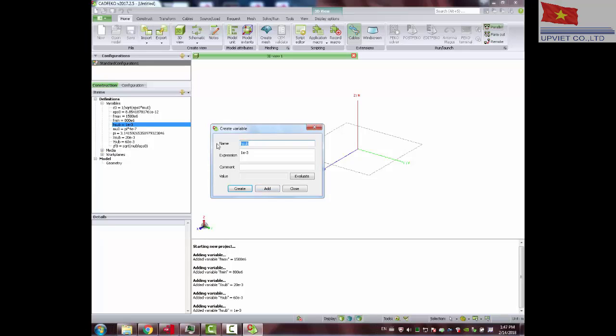The width of our line to get 50 ohm is going to be called W50, 1.94 millimeter. And this last parameter is the offset, 3 millimeters. I just forgot, epsilon R is 4.3.